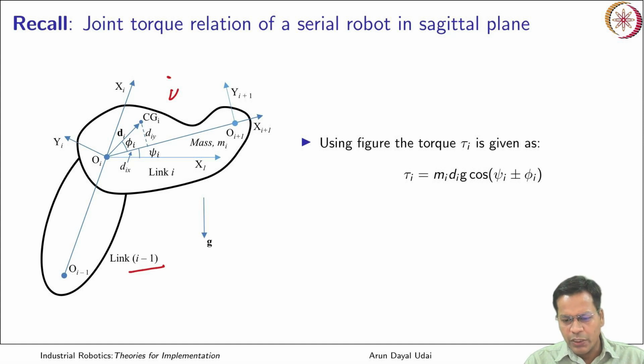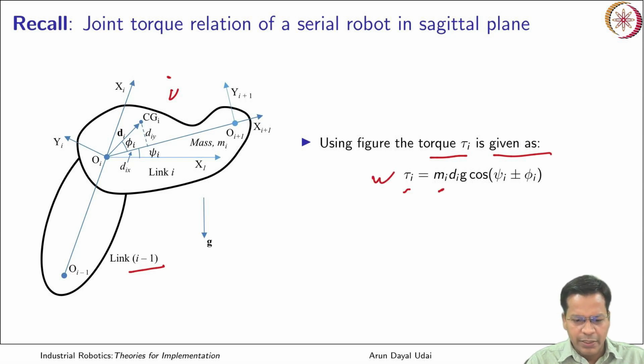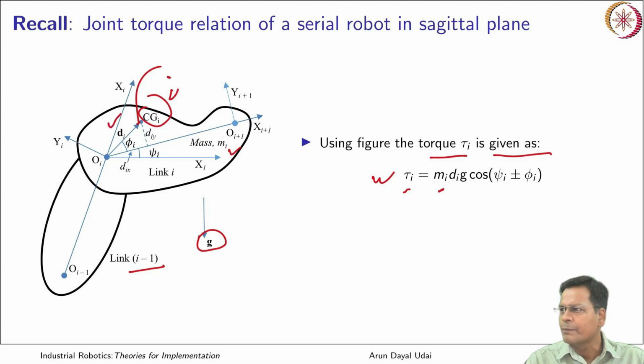In this figure you see torque I may be given as tau I, this is a scalar value. mi is the mass of this link, the ith link, g is acceleration due to gravity, okay. So that is the force which is acting, mig is the force acting downwards, and this is your center of gravity location here, okay. And you have a vector given by di that connects the axis of rotation to the center of gravity location, okay. This vector is in plane.